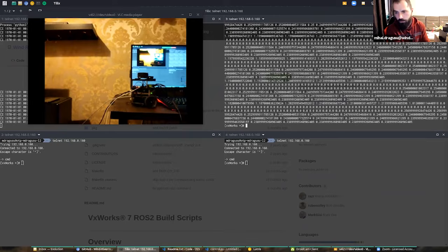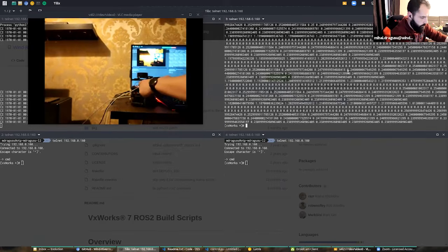We don't want 2 frames per second, or even worse with our Raspberry Pi setup. So what we're gonna do is capture images and send them over to my machine, process them, and send commands back to the robot to turn. In order to do that, I'm going to connect a USB camera to our robot.